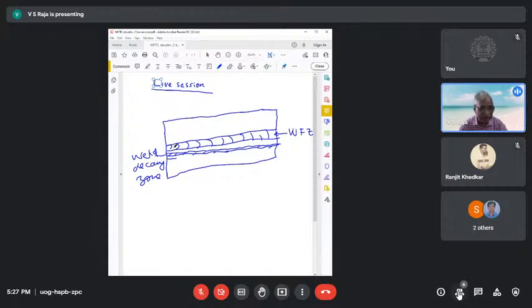Here it becomes a liquid, whereas in this region it doesn't become a liquid; rather the transformation occurs within the solid. Some phases really occur. When you talk about steels, for example, there is a wider region of heat affected zone where there is a change in hardness, change in phases and all.